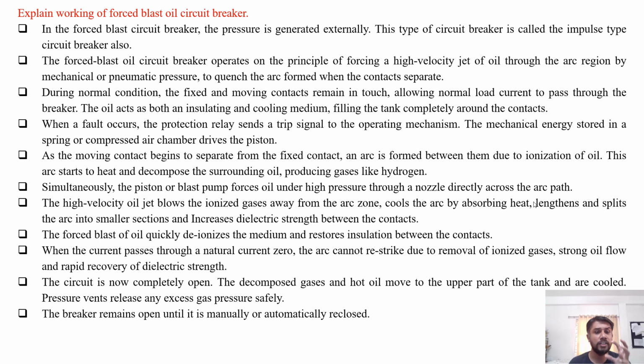The forced blast of the oil quickly deionizes the medium and restores the insulation between the contacts. Now when the current passes through a natural current zero instant, the arc cannot restrike due to the removal of the ionized particles or ionized gases, strong oil flow and rapid recovery of dielectric strength. As the rate of rise of dielectric strength is high compared to the restriking voltage, the arc does not restrike again.